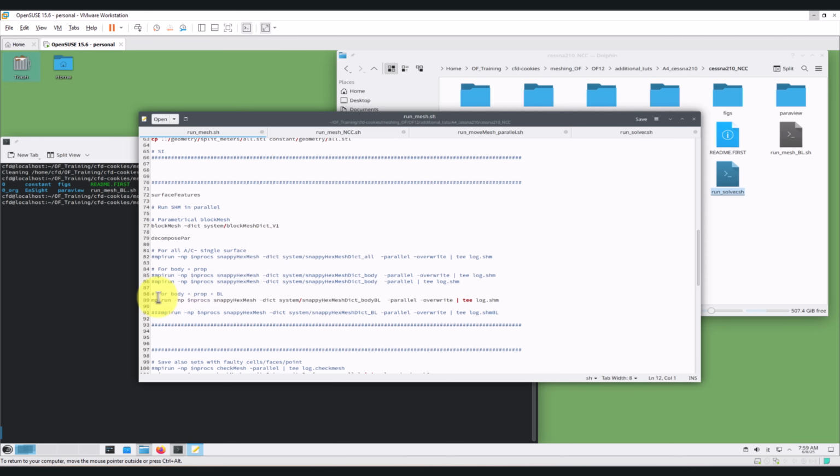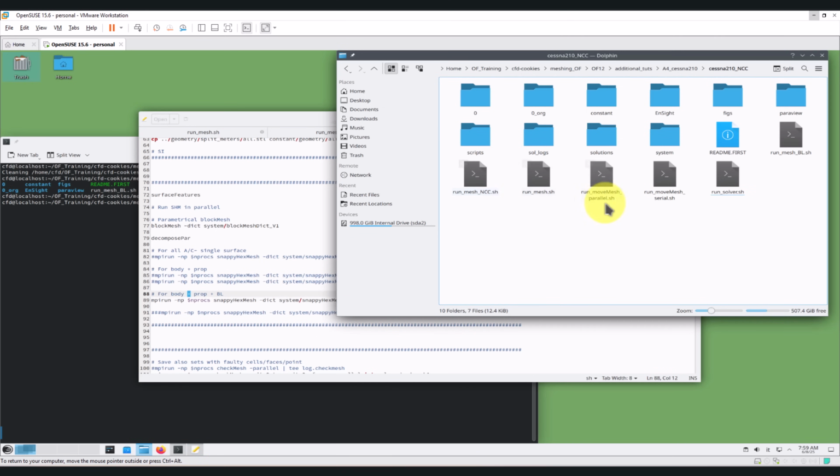Pay attention that in this case the script is also doing the mesh and the boundary layer at the same time, so that we have the transition, the body and the propeller, everything. But remember, you can also do this in individual, separate steps. You can do just the mesh there, and then do the BL. You have the script here also.